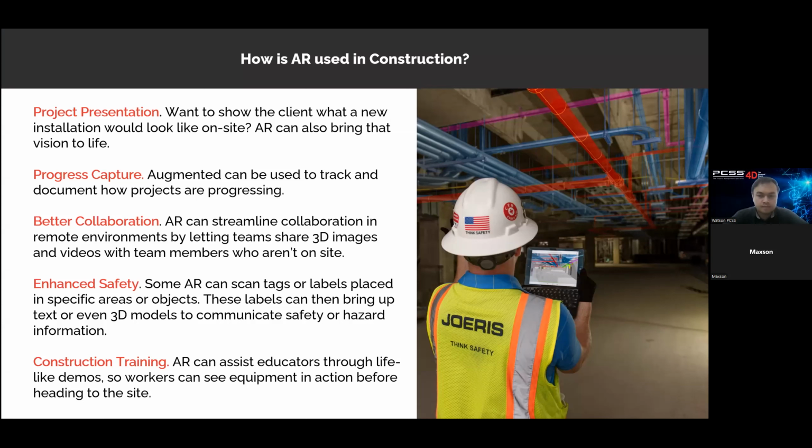So we can actually compare what's on site, what has been fixed on site, to the digital model. We can know whether it was fixed correctly, what is missing, or what has been done wrong. Maybe a pipe runs too far away, 1 meter away, and you can assign issues to it. You can put in comments, and when you are connected to the internet, the issue will sync to a CDE. For example, Gamma AR syncs issues to Autodesk Docs or the Autodesk Construction Cloud solution. So you can do this kind of thing.